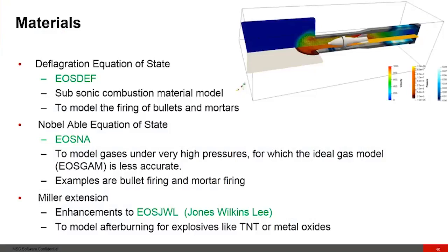We also added some explicit nonlinear materials for subsonic combustion, progression of deflagration. So you can see we added some materials for equation of state for deflagration. These are the subsonic combustion material models to model the firing of bullets and mortars.